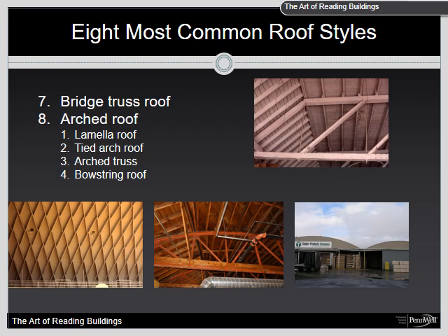These roofs are found on various types and sizes of commercial buildings and were constructed during the historic and industrial eras. The wooden truss members are built from rough-cut, solid milled lumber of 2 by 12 inch size or larger, depending on the size of the building. This usually constitutes a heavy grade of construction. Vertical tie rods between the upper and lower chords may be used for additional support.